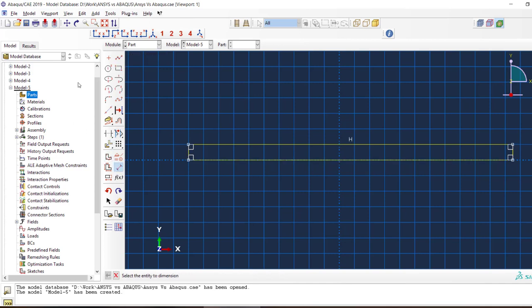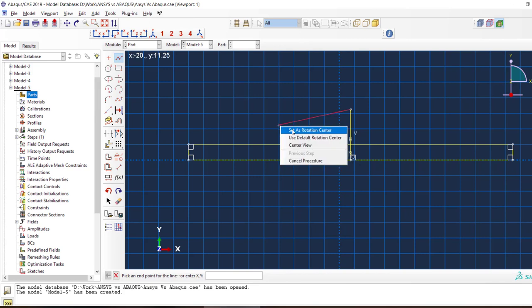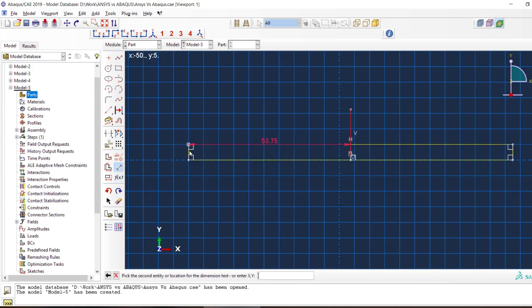And we first need to create a, this is the center point and it highlights it. Oops, I'm gonna hit escape, and now we get a reference dimension to be 48. Let's make it like 50, 2 inches more than that, and now we can split it.